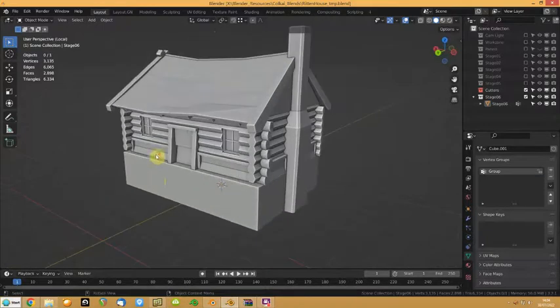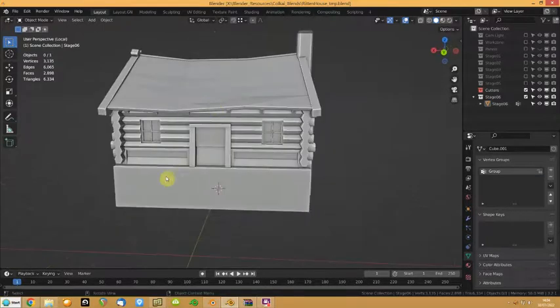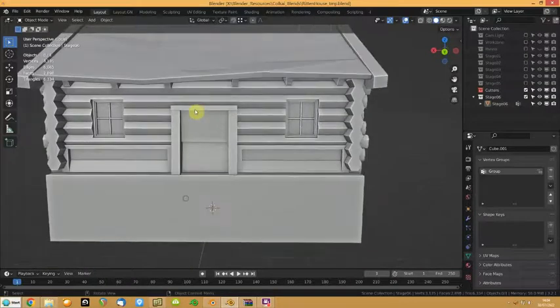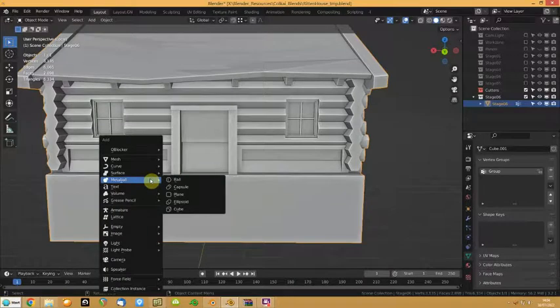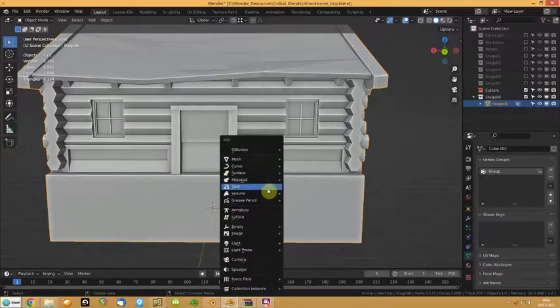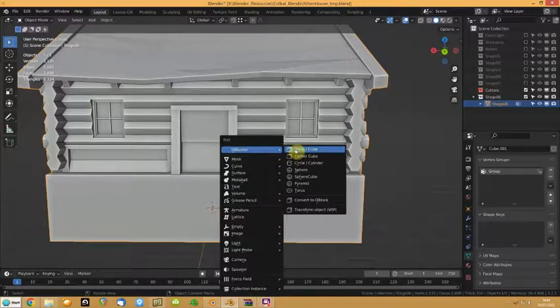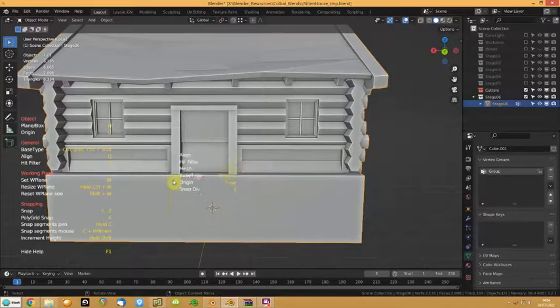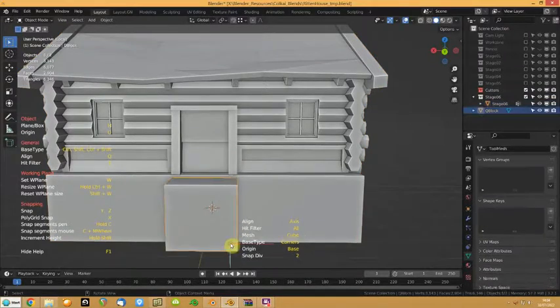One thing I will show you, I'll just show you how useful QBlocker is. So let's say this was the original one and you wanted to rebuild that doorway. I could do a Shift A. I've selected that object, Shift A, QBlocker, and add a plain cube. And you can see it's orientated to that, so I can just drag that down, pull it out, click, right click,